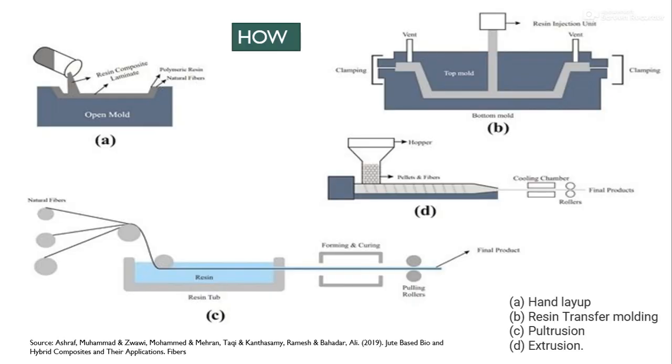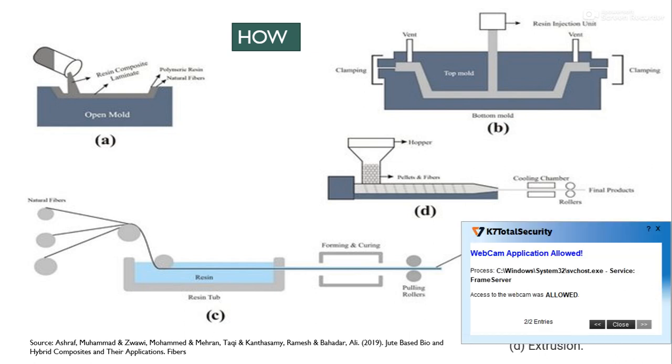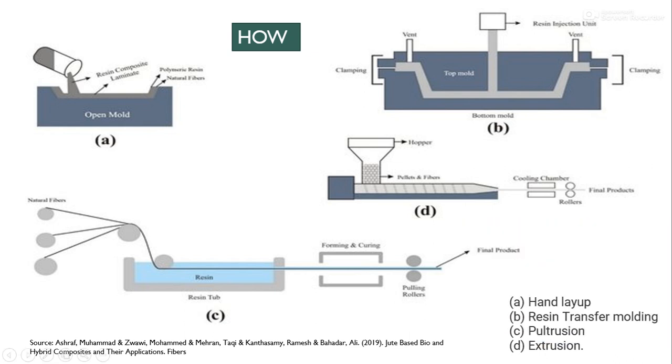How are composites made? Mostly the easiest one is the open mold process, and we have the closed mold process, and the filament winding process. We also have infiltration and extrusion processes. So this is about the basics of composite material. In the next class, we will see in detail how to manufacture a composite material and what processes we have. Thank you.